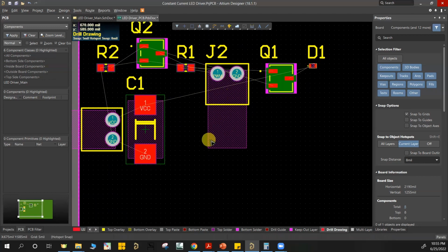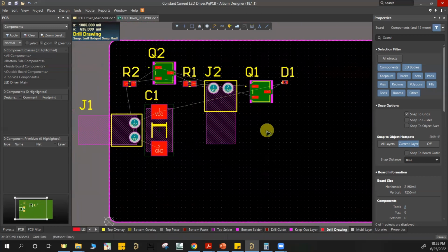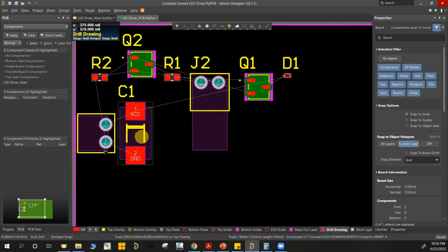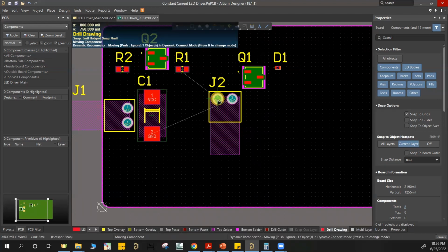This is a very simple design, but for example, if you had components such as microcontrollers or ADCs, or other components that are more prone to noise or interference from devices upstream, like the VCC in this case, it's always best to make sure they're immune to those noises by implementing the right noise reduction techniques, such as using these input caps, decoupling caps, and things like that. So now that the input caps are connected, we just go through the same design, making sure that everything else is placed properly.